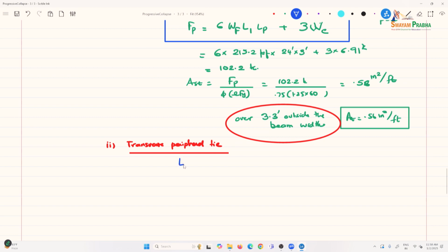And so L1 is LT, which is 36.5, and the cladding, if you can just help me with this number please, 1.2 times 20 PSF times 12 times 36.5. So this should come to about 10 point something, 10.5. Thank you. FP, again hold that number.